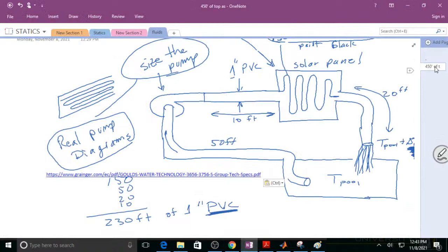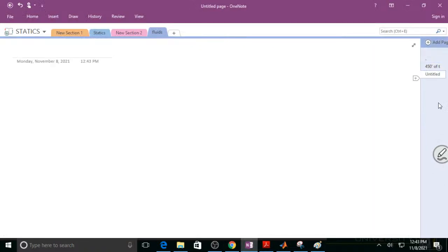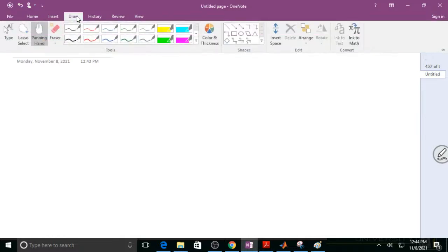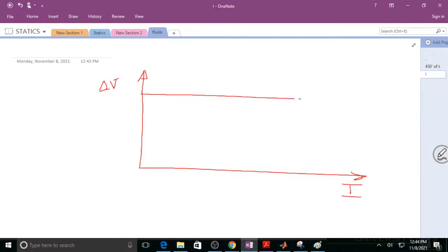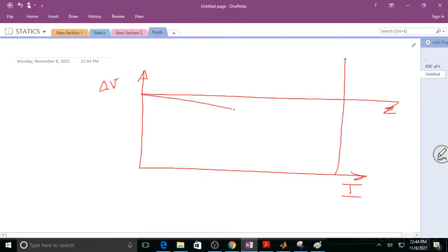So pumps are like circuits. They're just like circuits. This is the part I love. So if you look at delta over current, a constant voltage source looks like that, a constant current source looks like that, and a real pump looks like that. And that's just what a battery does.